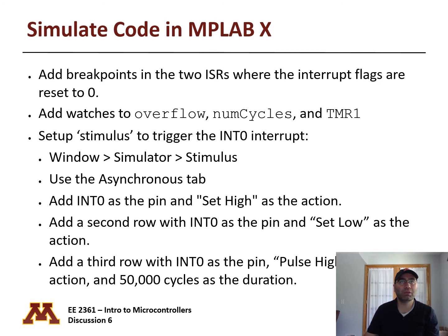How do we do this? You go to stimulus from the Windows tab on the top, simulator, stimulus. We did this a couple of times in other lectures. Use the asynchronous tab, add INT0 to pin, and set high as the action.